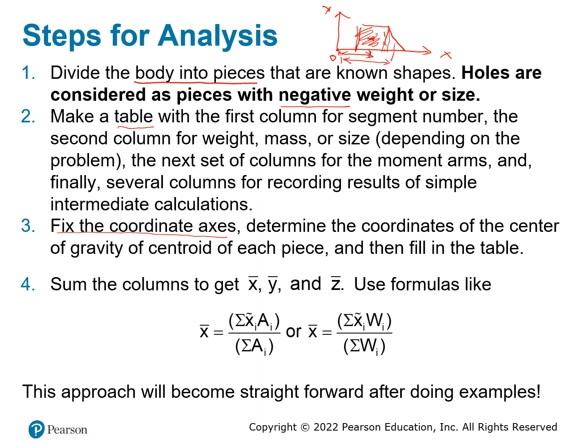So this is one of the bases, this is another one of the bases. So it's going to be 1/3 from here, 1/3 from here. Then you can find the location of each one of the centroids of the shape. And then you just use this equation to find the solution. So for the x, you put x multiplied with that. This one simply represents the locations that we just talked about.